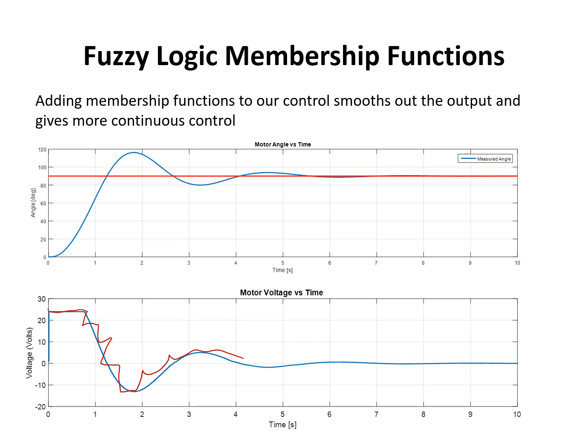The output might not necessarily be as good as the PID controller, where the tuning is much more simplistic in essence, but you can get a non-linear control output from the system based on the amount of functions you use, how large the steps in between those functions are, and how non-linear those steps are in fact. So this is the conclusion of control, where we look at the PID controller, which is a more analytical approach,